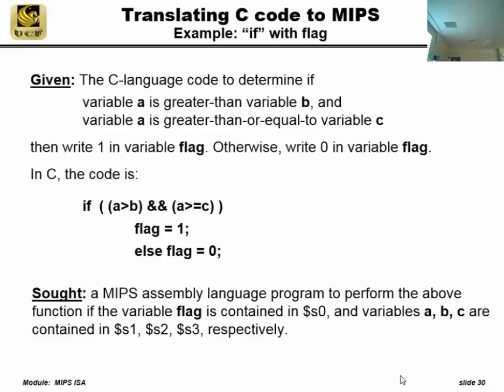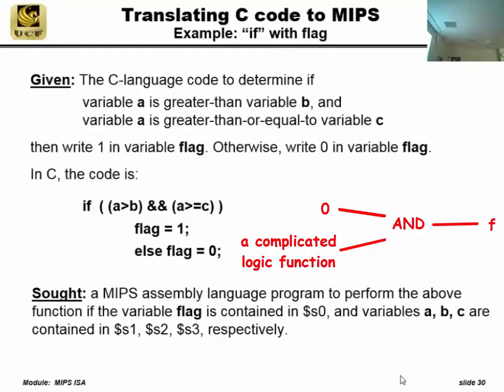This is a common thing to do in a circuit design class. Maybe you even had this question, right? Here's an AND gate. And we have a whole bunch of gates over here and some XORs, and an OR, and a whole bunch of gates over here. And then we have an AND gate at the end. What's F? 0. Do you need to calculate anything?